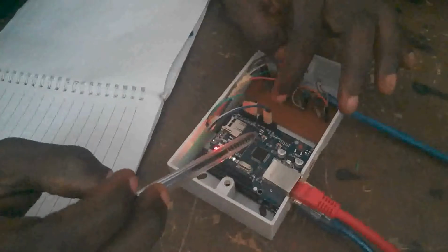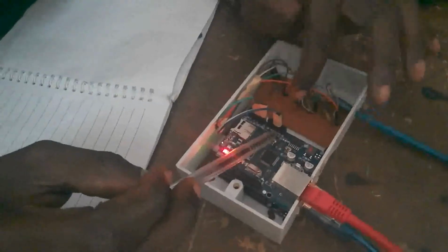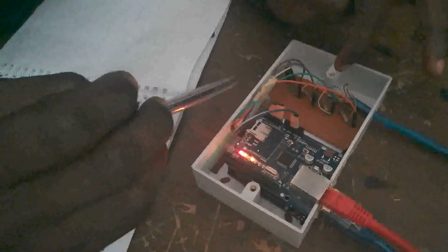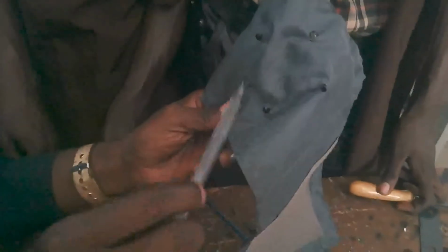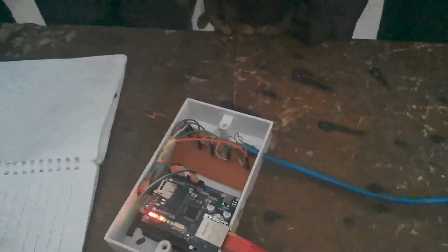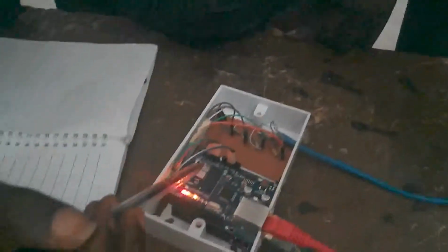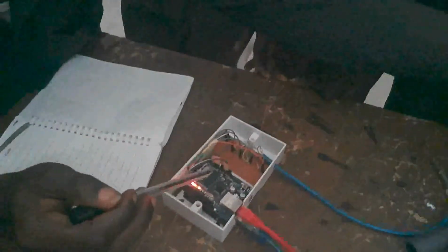At this point, we have to link the 10K resistors to the board, combining it with the Arduino Uno. If you check at this point, we have the 5 volts, which is connected to the board. The ground is also connected to the board. Since I'm using more than one thermistor, I'm using up to 4: 1, 2, 3, 4. So I have to connect the first pin of this NTC thermistor to A0, the second pin to A1, the third pin to A2, the fourth pin to A3.